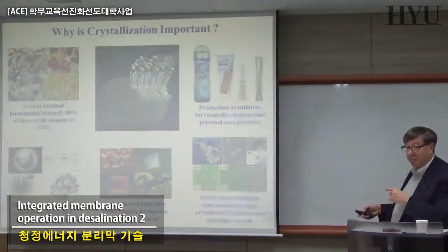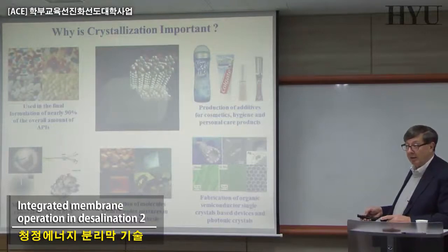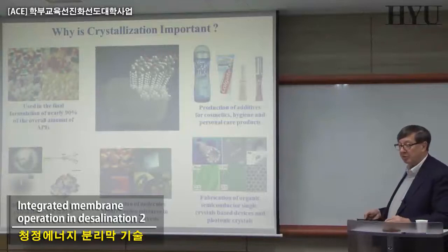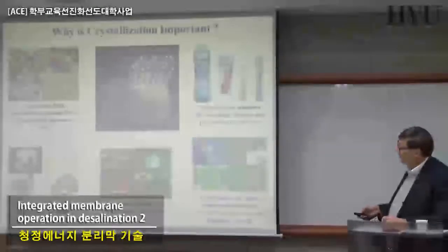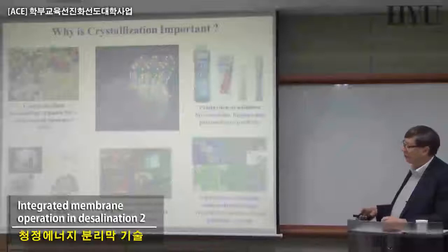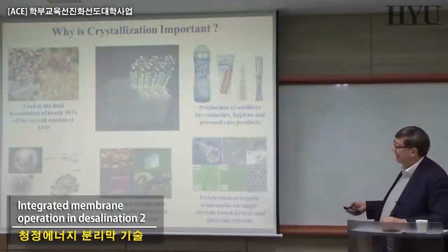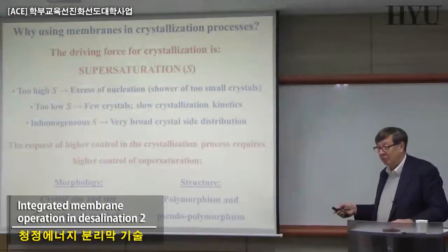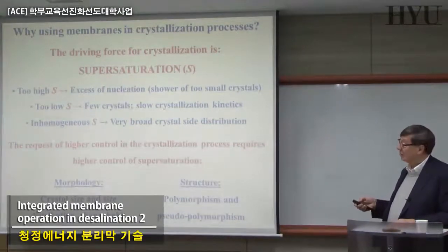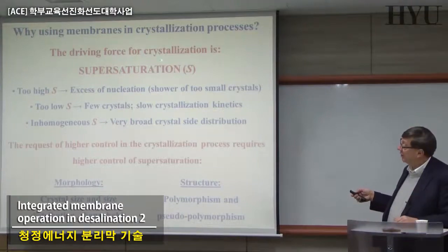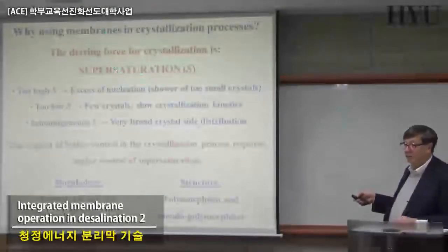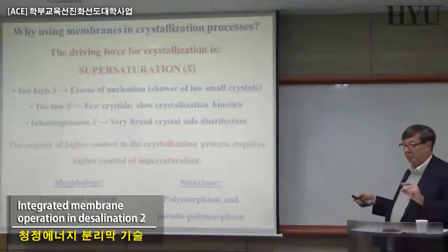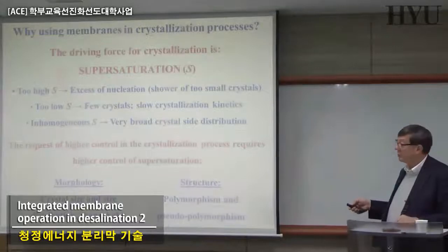Crystallization, which is a very important technology today, is one of the most important final formulations of most of the products you are producing for a lot of different kinds of application, from crystals to catalysts, pharma, etc. If you learn the situation today with crystallization, you learn that the quality of your crystal is related to this step here, to create the supersaturated solution to induce what we call heterogeneous nucleation.